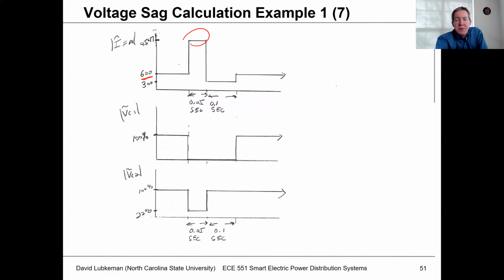So the current goes from 600 to 300 because you had 300 amperes on that breaker that just operated. So that current level drops down. And then when that circuit breaker closes back in again, you see the recovery of the 300 amps. So this is what we would see at the top in the substation monitor.